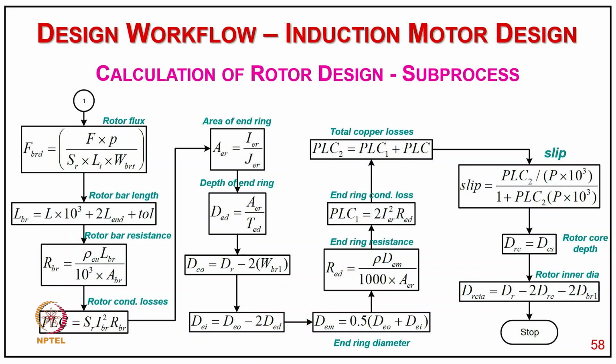Then we calculate the slip from that, typically the full load slip, and then the rotor core depth, followed by the rotor inner diameter, and we stop. So this covers the whole rotor design process.